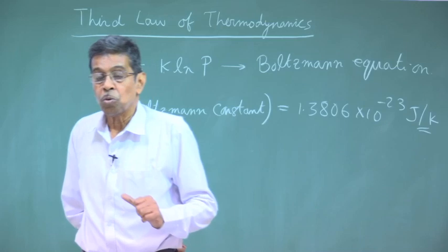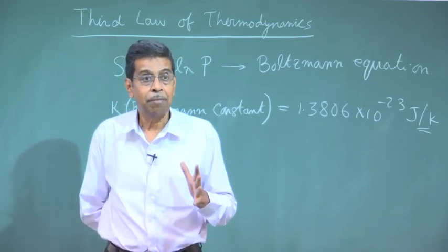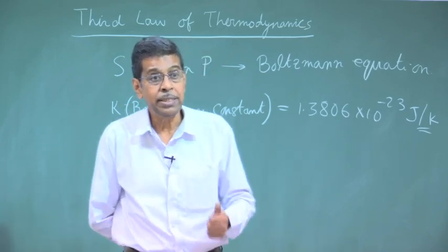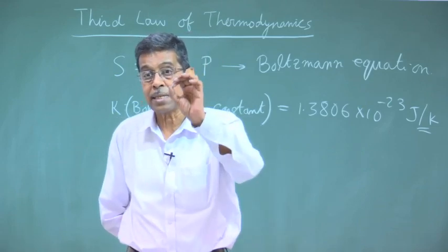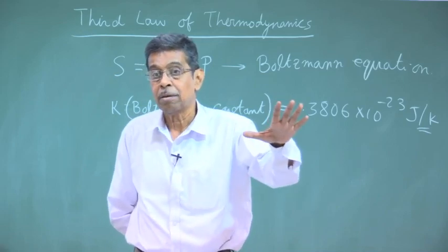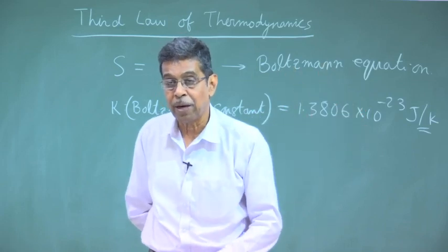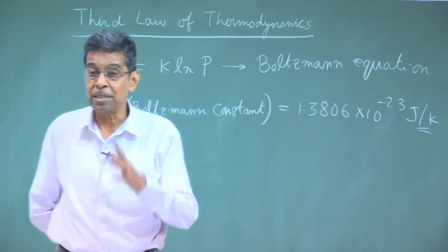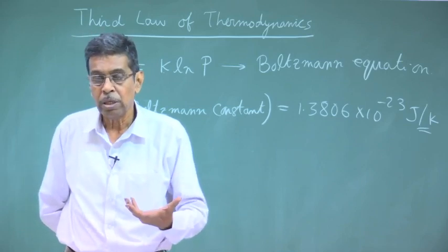Now, with this Nernst-Simon statement, we can have some idea about the absolute entropy. How it is useful in engineering calculations: to have a common base so that we can ascribe the entropy values at different states from its changes calculated by our well known formula in classical thermodynamics through reversible heat transfer. That common base is very important in chemical reactions, which has not been taught in this course.